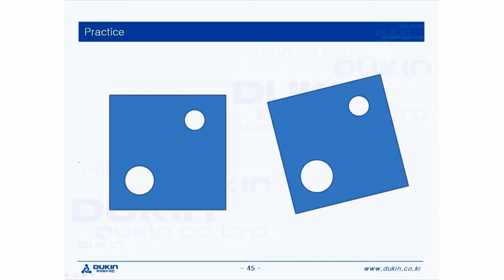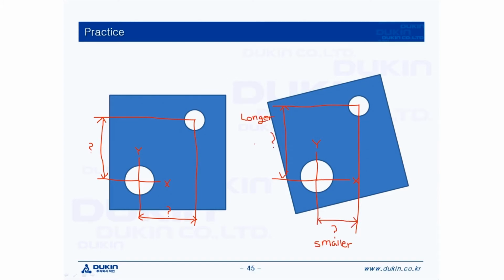Okay, let's take a look at this example first. They're the same part, but the right one is more rotated than the left one. So in these two cases, the left one's X and Y values could be almost the same position, but the right part's X and Y values for the smaller circle would be a little different than the left one, because the position is different. The X value would be smaller and the Y value would be longer than the left part, because the right part's rotation is not constrained. So to do the rotation for this part, the basic dimension, which is indicated as 40, would be the reference. So let's learn how to do the offset distance, and let's take a look at the practice.